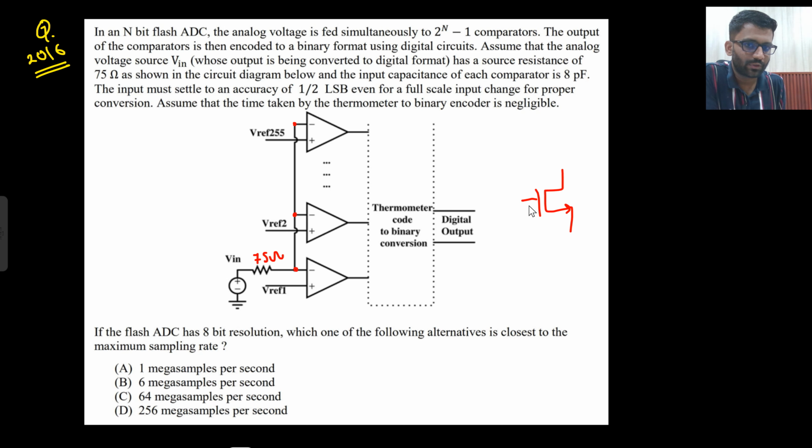It would be made from some MOSFETs or BJTs. This is how your op-amp would be made. And MOSFETs and BJTs will have some input capacitance, like all the components. So that will effectively become the input capacitance of the op-amp. All these op-amps, in any IC design on a chip, will have some input capacitance.